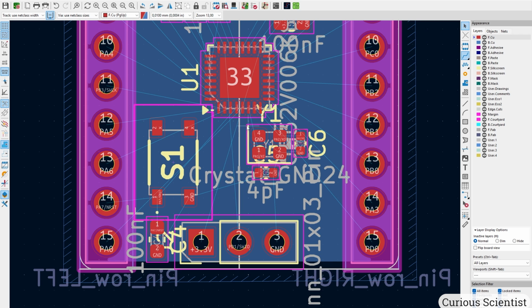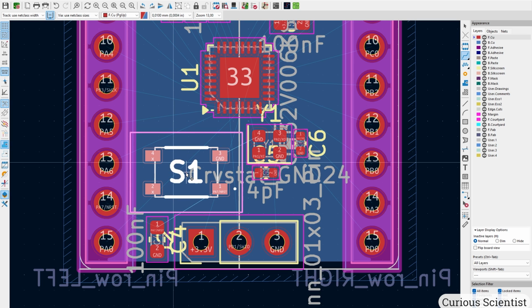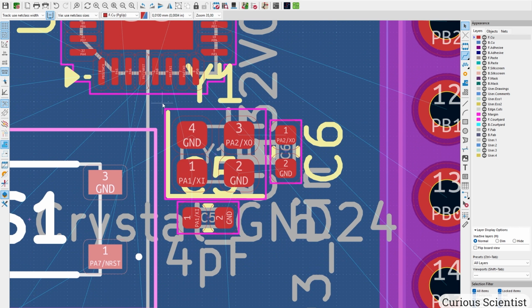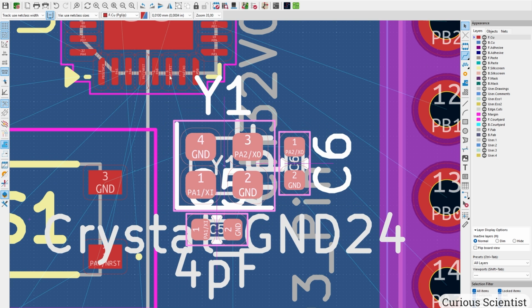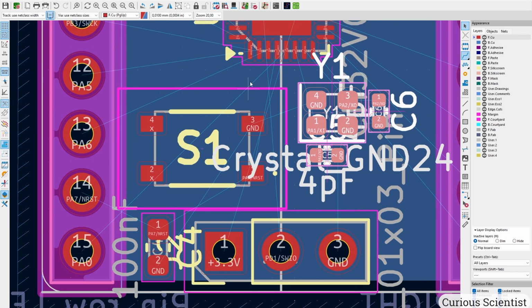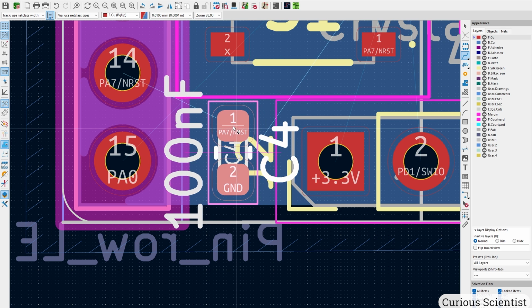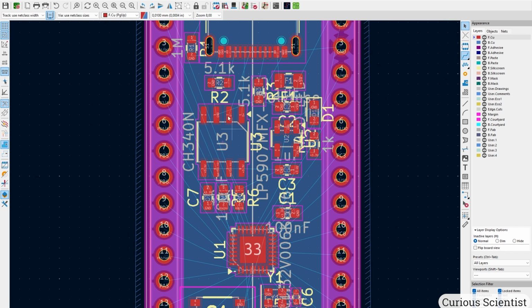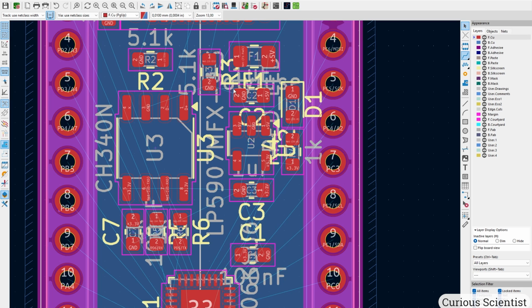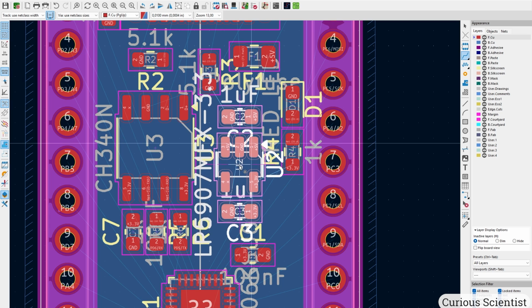First of all, I can see that here this button causes a little trouble. So maybe I rotate it this way and bring it down here, and I can allow this to be a little bit further from the microcontroller. We are talking about maybe 2 millimeters, so that should still be enough. And this should also still be fine with the capacitor. So let's place it here. The microcontroller stays. Then the chip can stay here, but here I have a bit more crowded area, and probably bring it a bit closer here.